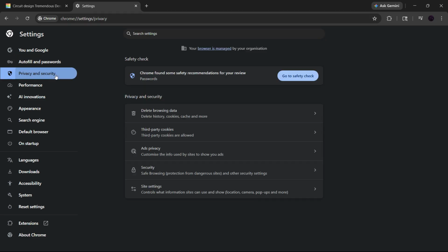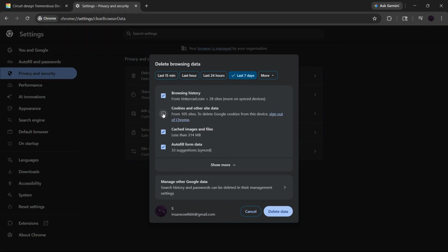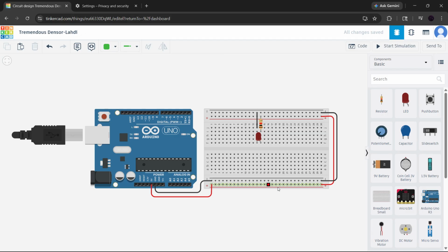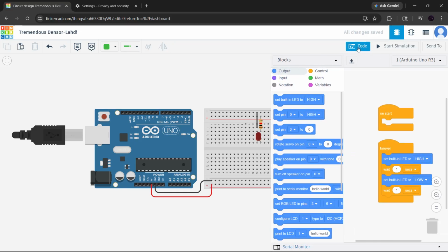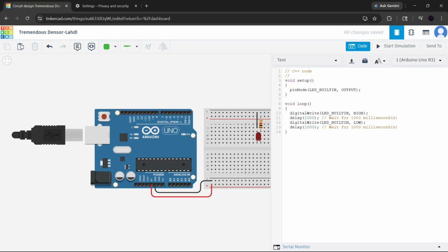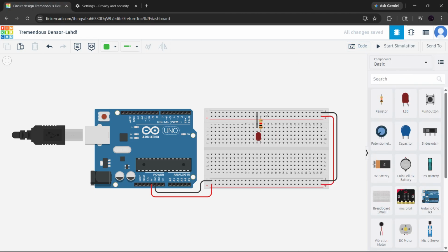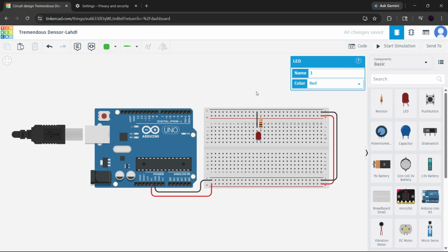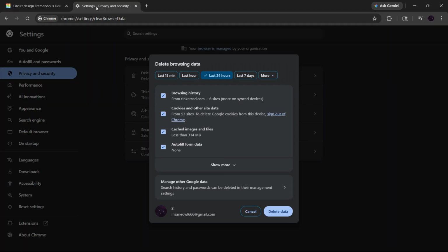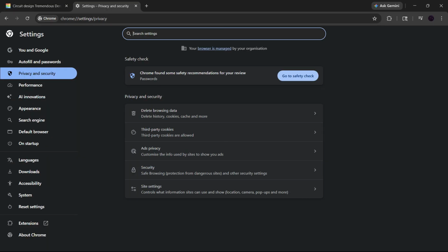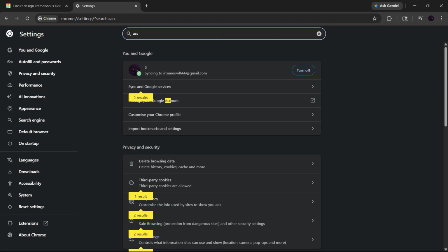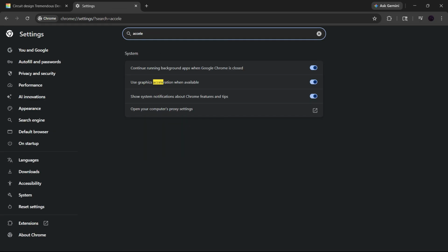So to recap, if your Tinkercad simulation start error appears, first inspect your circuit for short circuits and incorrect breadboard placement. Then check your code for missing semicolons, broken logic, or loops without delays. After that, verify your resistor values, power source, and component ratings so nothing unrealistic is being simulated. And finally, make sure your browser is not the problem by enabling hardware acceleration and testing in an incognito window. If you follow those steps in order, you'll solve most Tinkercad simulation startup errors very quickly.